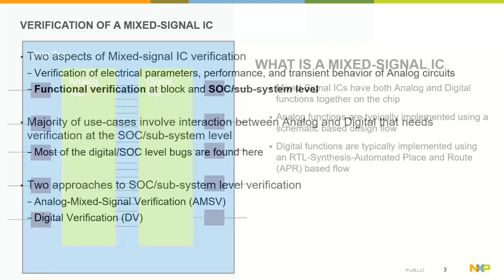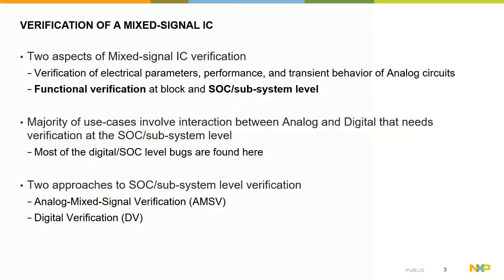Then, when it comes to verification of these mixed signal ICs, there are 2 aspects. The first is the verification of the electrical parameters and the performance, and also the transient behavior of analog circuits. And then the other aspect is the functional aspect, where we are trying to verify the functionality of the IC, both at the block as well as at the SoC or subsystem level.